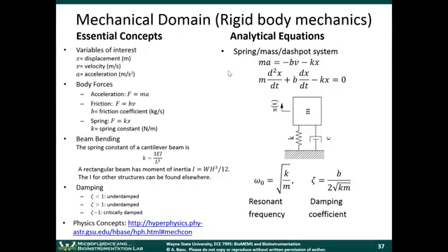One of the things we're interested in is how fast does the object move? How quickly does it get to its equilibrium position? Does it vibrate? Does it resonate? If a sudden acceleration causes the device to vibrate, at which frequency will it vibrate? It turns out a lot of accelerometer sensors take advantage of vibrations. They run the system at the resonant frequency because that's where you get the best energy characteristics, or the least energy loss. All right, so this is the basic spring mass dashpot system.